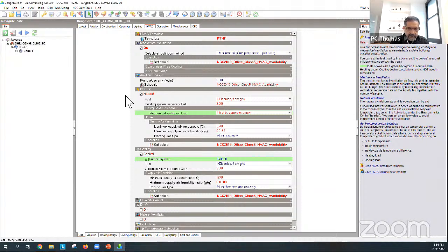When you're doing a real design, you should zone the air conditioner. So you have different zones, and then it'll work out the total for the building. And use some virtual partitions if it's an open plan office. Talk to an air conditioning engineer. Usually they like about 4 meters to be a perimeter zone. And then you can work out the numbers as is. Okay. So let me do that second run, and then we'll answer a couple more questions.